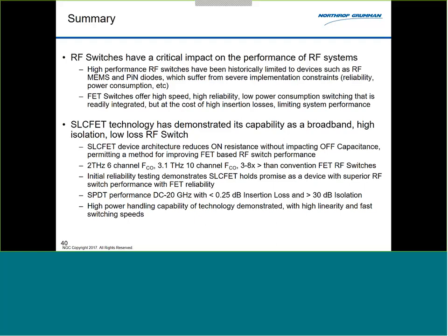The issue really comes if you have traps and you're having to fill and empty traps back and forth. That's the kind of cycling that really hurts you, because you can develop these virtual gates in the device, and those virtual gates can kill your device in the sense that your device doesn't want to turn on, essentially. It doesn't respond properly.